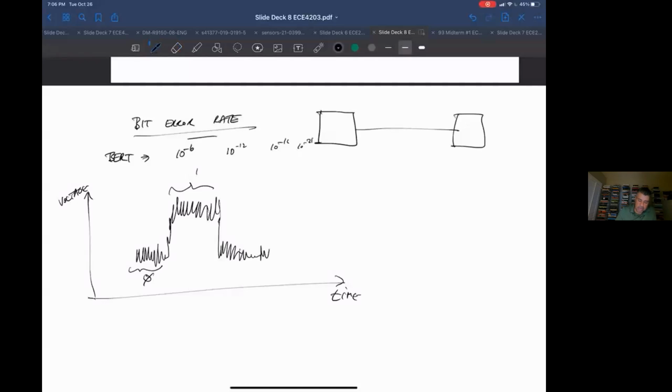It's not unusual, if you had a real fiber optic communication or cellular communication, to have a very low signal to noise ratio. So in this case, this stuff here would represent noise, and this value looks like a signal, voltage, whatever it is. It's got a bunch of noise on it. The reason it looks so bad is typically this delta V, by the time you're doing a fiber optic communication, might be like a millivolt or something coming out at the end of your channel.